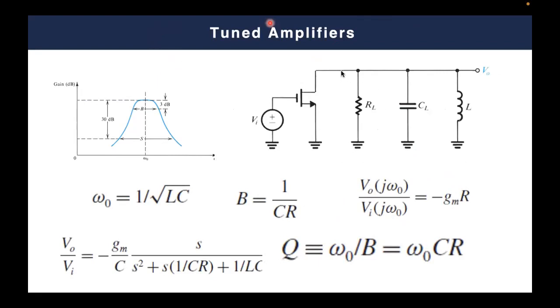So it is as if you have a resistance here, which is R node. So simply your gain now will be negative gm times R parallel to R node. You know gm, which is 5, I think. You know the gain, which is typically negative 10.